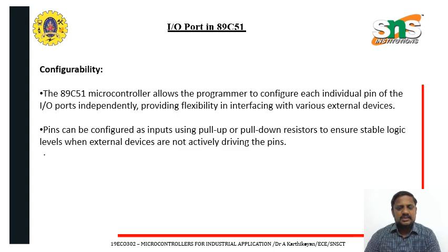Now, what is configurability? The 89C51 microcontroller allows the programmer to configure the individual pins of the I/O port independently, providing flexible interfacing with various external devices, such as traffic light control systems and other devices. The pins can also be configured as inputs using pull-up or pull-down resistors, which enable static logic levels when the external device is not actively driving the pins.